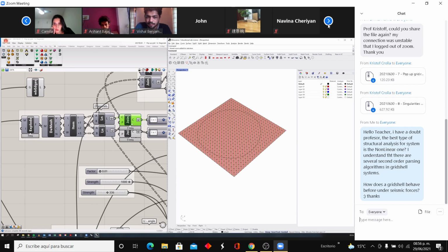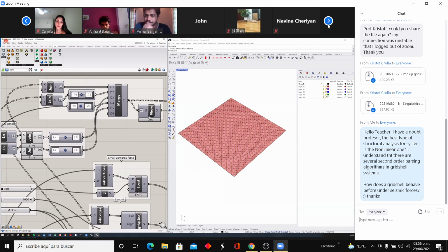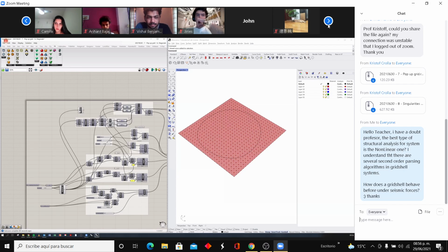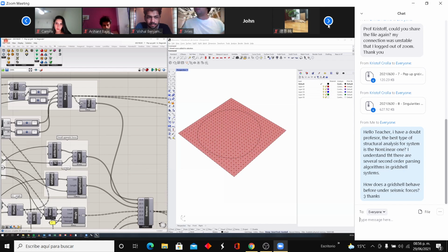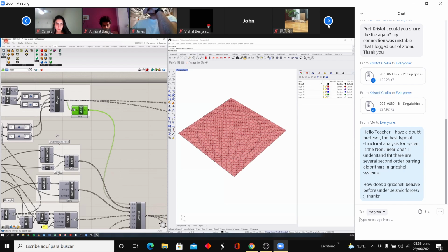So all you need to do is add that, merge that into the show button that I have added here in our goal objects for Zombie Solver. So you can add whatever you want here. This whole show button basically redraws geometry that you put in there through the control points that you have running through your algorithm. It just keeps track of the order of control points that Kangaroo is calculating, and it's reusing those to draw the geometry that you put in there. So that's how we've been doing the members, how you've been doing the mesh, and now how I'll be doing the diagonals.